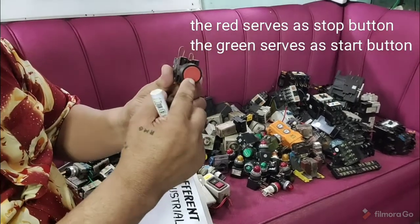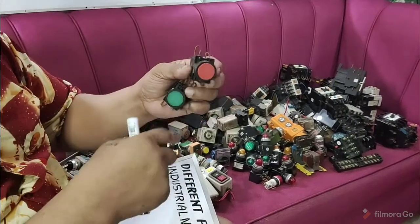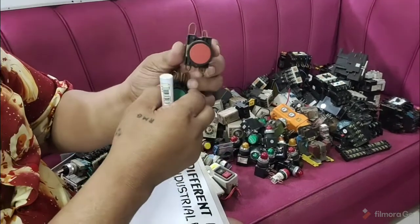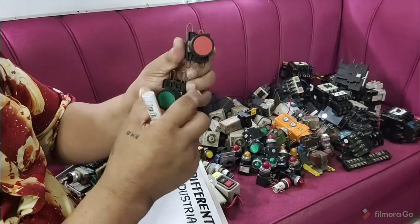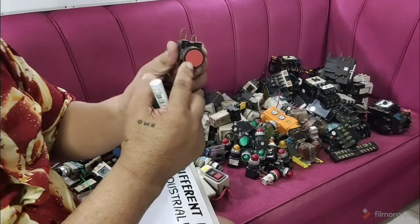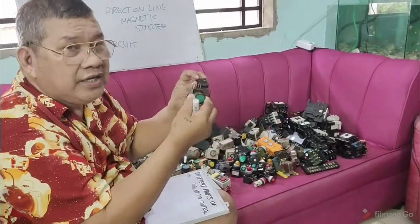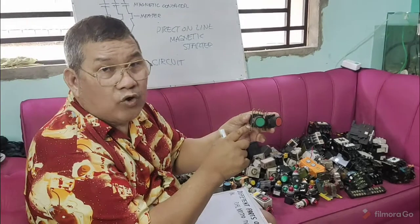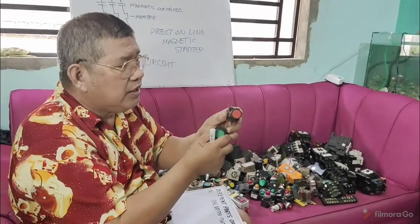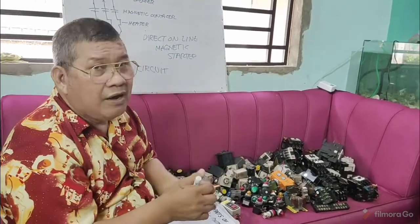Now remember, the red, you have a double contact. As I illustrated here, this one also has a double contact. So if you will be using this as your start and stop button, in this portion here, you will only use the normally closed. While here, you will also use the normally open. Though this is double contact, you will only use the normally closed and the normally open contact. So this is what we call flush type.